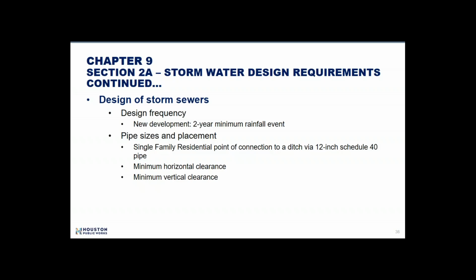Definitely no water. Water was eliminated a long time ago, and sanitary should have been eliminated a long time ago. But basically, at the end of the day, if there's any leakage, people say, well, I encase it. Encasing something doesn't make it any better. If something gets into the storm sewer system, then it creates problems. A leaking sanitary system creates a problem. A leaking water system creates problems because you can't really see it if it's leaking into a storm sewer system and clean water is coming out of it. You don't know if it's groundwater or potable water. And so they just want to eliminate the conflict.